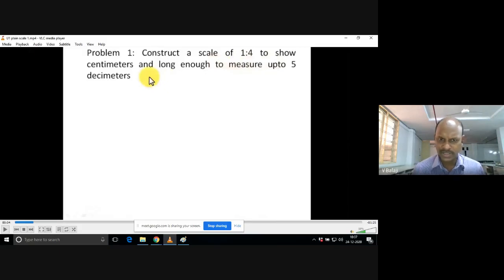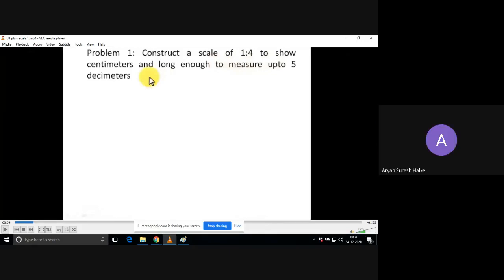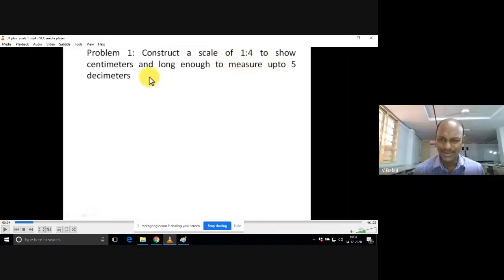I've already given some introduction, right? Can you guess now? 1 mm is equal to 4 centimeters. Okay, actually, it is the ratio. There will be no units. In other words, the drawing size we are assuming is 1 unit, but the actual is 4 units in length, or area, or volume, whatever it may be. The actual object is 4 units. We are reducing it to 1 unit.